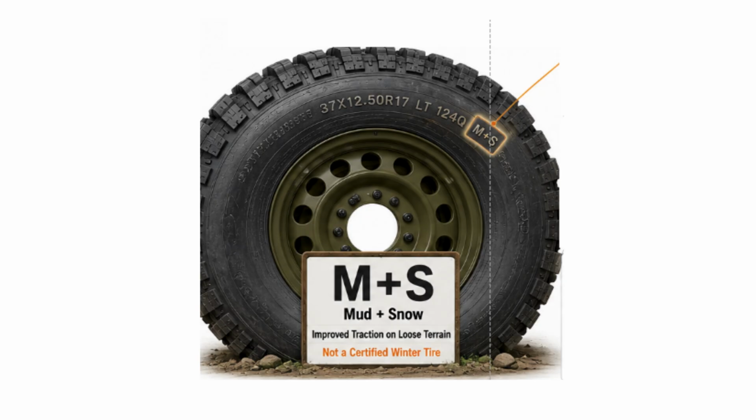However, an M+S marking is primarily a manufacturer's classification based on tread design. It does not necessarily mean the tyre has passed a certified severe winter performance test. Therefore, engineers should not treat M+S as proof of full winter capability. Tyre selection must still consider terrain, temperature, load, pressure, and operational requirements. For more demanding winter conditions, look for additional certified markings such as the Three Peak Mountain Snowflake or 3PMSF symbol.